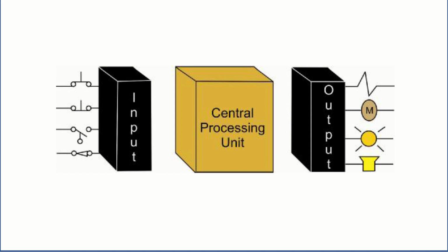Now suppose your bottle is coming. Let us first take the example of the PET bottles that are now used across the entire beverage industry. If we just think of a PET bottle through which a laser light can pass very easily, so we are considering a through beam sensor generating a laser light at the source that will pass very easily, and you are able to detect that yes, there is a bottle that is empty.